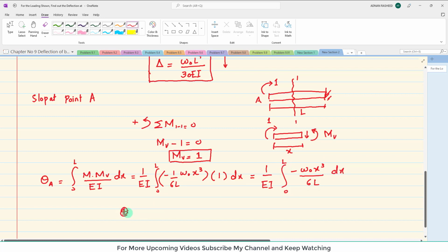So again, the slope at point A is equal to W naught over 6L. These are constants, so we will take them out. So W naught over 6L into EI, and we will only have integral of 0 to L of x cube into dx.